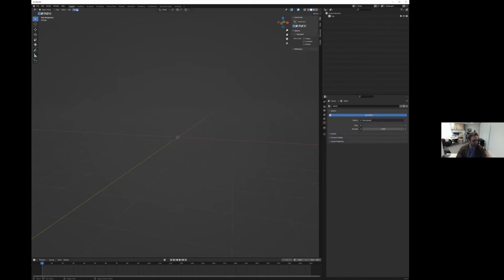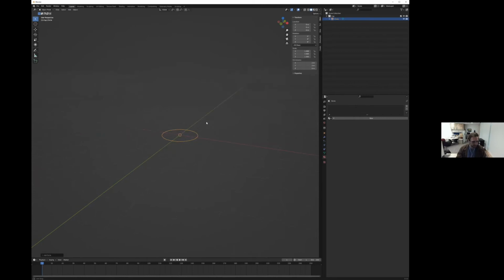So I'm going to delete it. You can select that, or you can do Shift A. Shift A will bring out that same panel. And as I mentioned, we're going to do a circle. So let's go ahead and create a circle. And here we are. So we are looking directly at a circle. We can zoom in. If we press edit, we can see all of the different edges, and we can see all the points. Okay, so I think this is 32 or 64 something vertices for it.